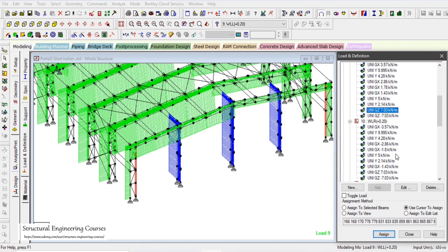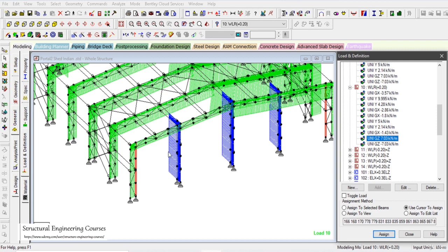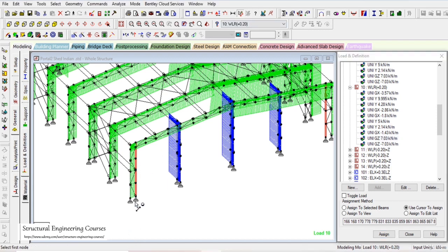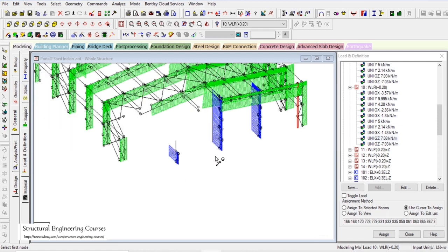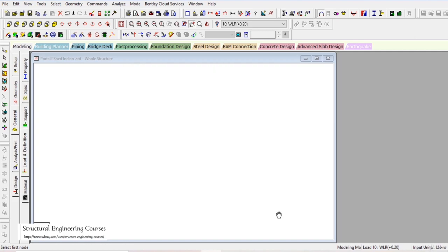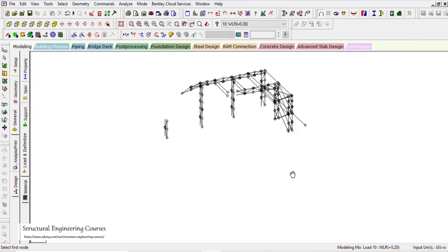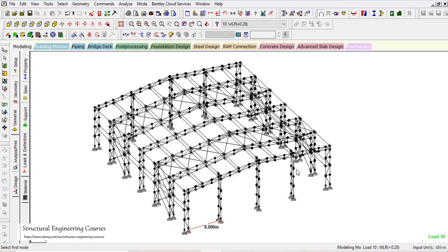Similarly for the other wind case, for example here also. So 7.03 divided by 2, because the effective span of this arrangement is only up to this point here. So on this column basically the loadings are biaxial, that is from this direction also and this direction also. So this was just a small addition or alteration that you do need to do on your own for the correct analysis and design. So see you in the next lecture.